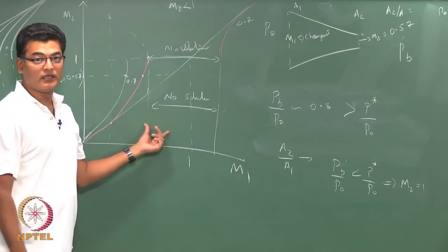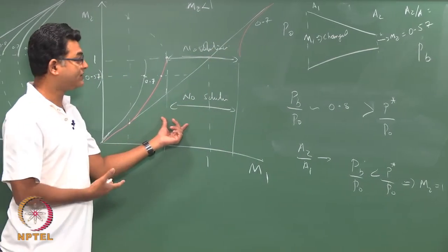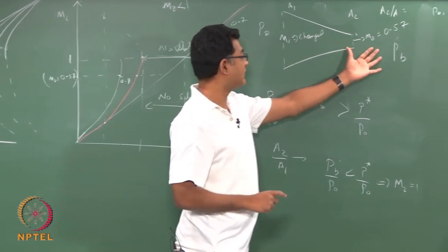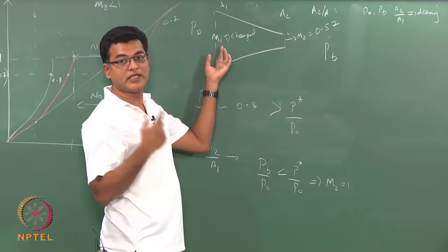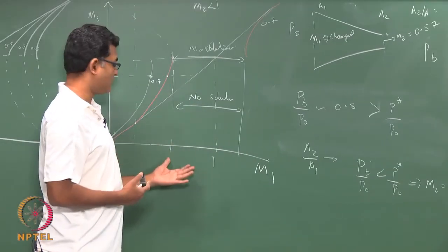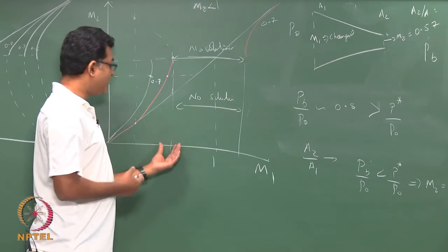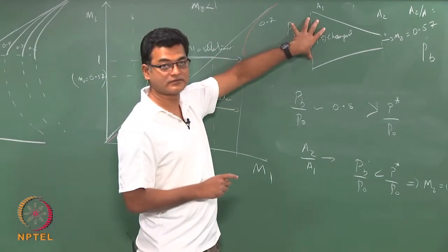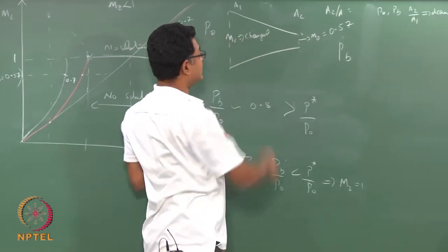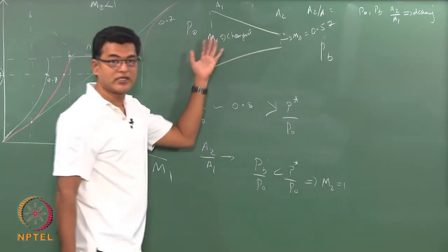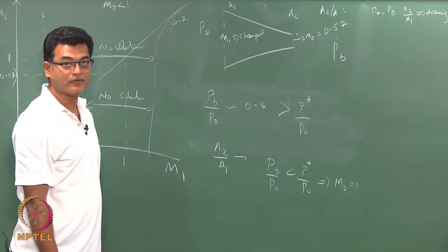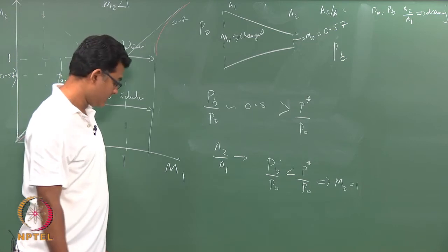I see that there is no solution to this isentropically. So, there is some non-isentropic process that is going to happen which will automatically change my M1. So, this is not a possible way of doing it. So, my M1 will somehow be changed. There will be pressure waves going in this direction, which will change my static quantities and change the pressure values. All right.